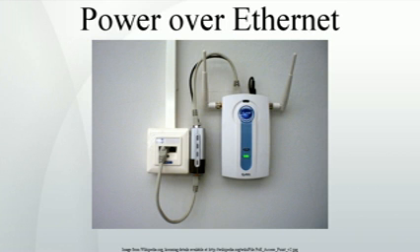Standard development. The IEEE standard for PoE requires Category 5 cable or higher for high power levels, but can operate with Category 3 cable if less power is required. Power is supplied in common mode over 2 or more of the differential pairs of wires found in the Ethernet cables and comes from a power supply within a PoE-enabled networking device such as an Ethernet switch, or can be injected into a cable run with a mid-span power supply.